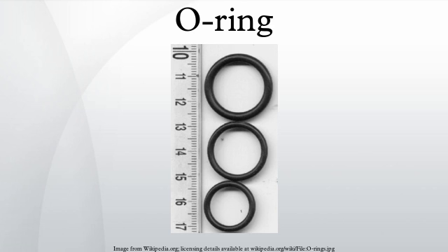Theory and design: O-rings are available in various metric and inch standard sizes. Sizes are specified by the inside diameter and the cross-section diameter. In the U.S., the most common standard inch sizes are per SAE AS568E specification. ISO 3601-1:2008 contains the most commonly used standard sizes, both inch and metric, worldwide. The UK also has standard sizes known as BS sizes, typically ranging from BS 001 to BS 932. Several other size specifications also exist.